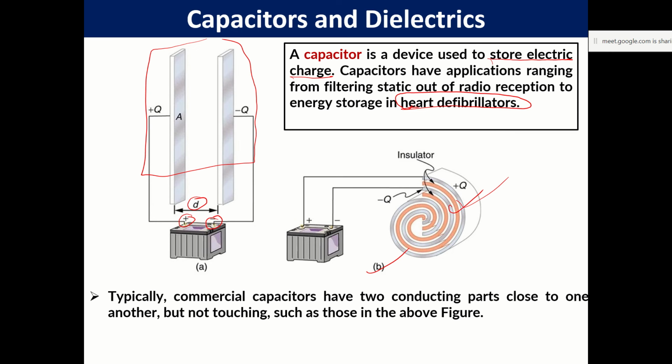So what you have essentially is two parallel plates connected to a battery, and the space that you see is actually air, vacuum, or any other insulator. Between two parallel plates, you have to put some gap. The gap also defines the thickness. So it has to be an insulator of a certain thickness, and that becomes the distance between the two plates.